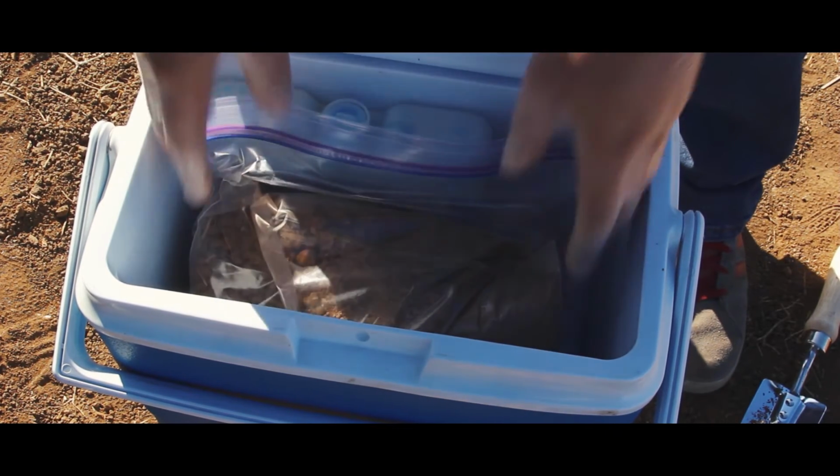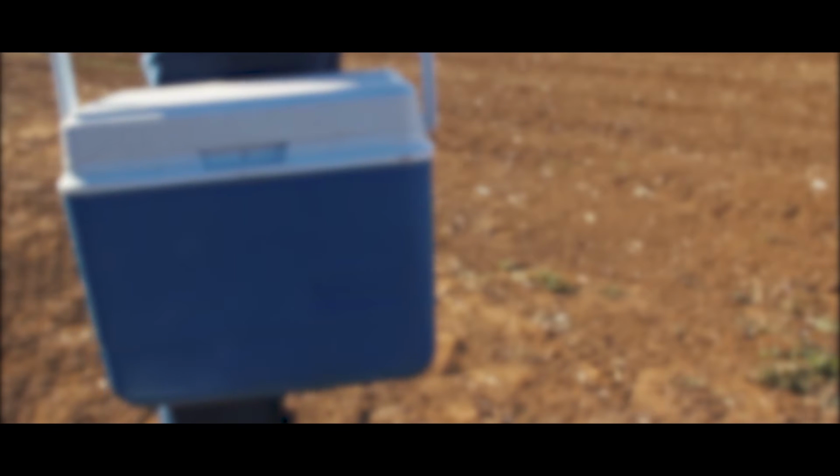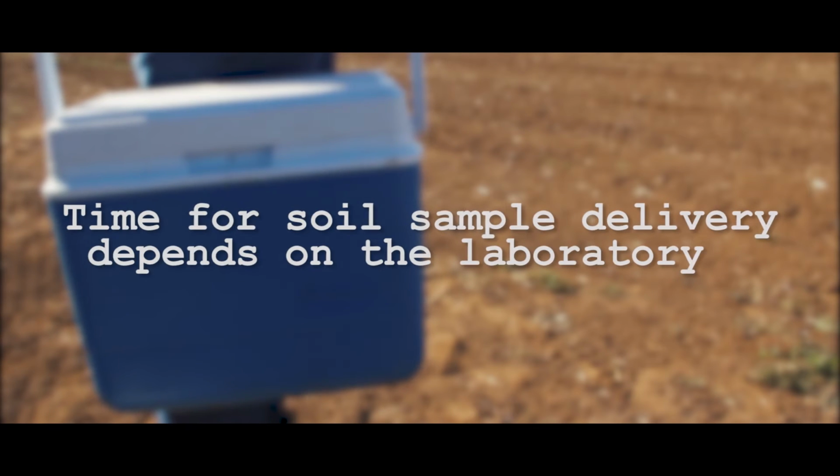After collecting the sample from each field location, place the sample on ice in a cooler. Transport the sample on ice to your contract laboratory as soon as possible. Most labs will have a time limit on how long you have between sample collection and delivery at the lab in order to ensure a valid test result.